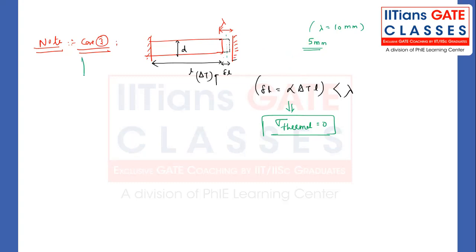So for case number 3, to have thermal stress not equal to 0, alpha into delta T into L must be more than lambda. Then only it will be hitting the right support. When it is just hitting the right support, then only Newton's third law will be applicable, and the reaction forces by the support will come into the picture. Getting my point?